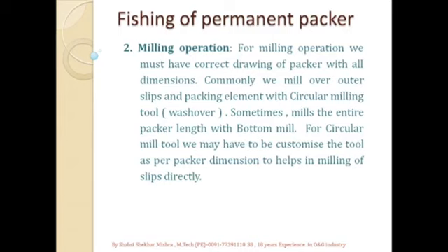So if we don't use the correct one, then we may have to mill down all through the body to reach the sleeve. Sometimes we mill the entire packer length with a bottom mill. So it is another way of retrieving the packer.